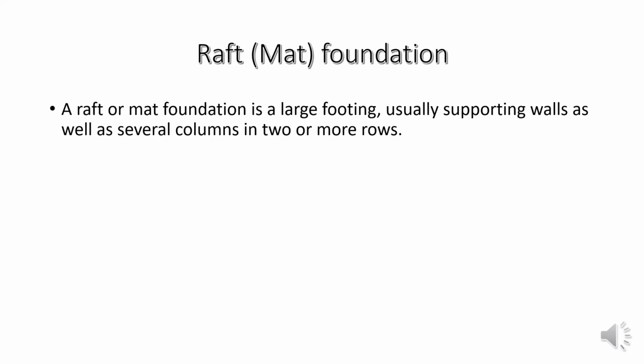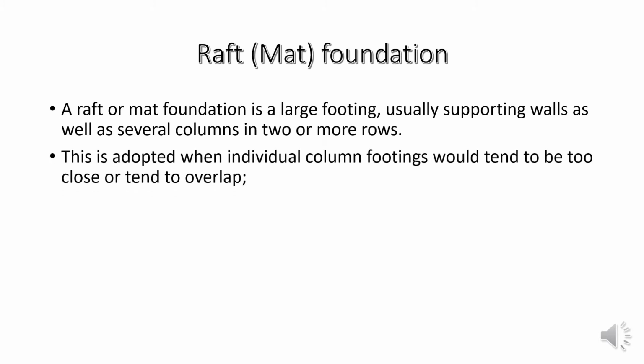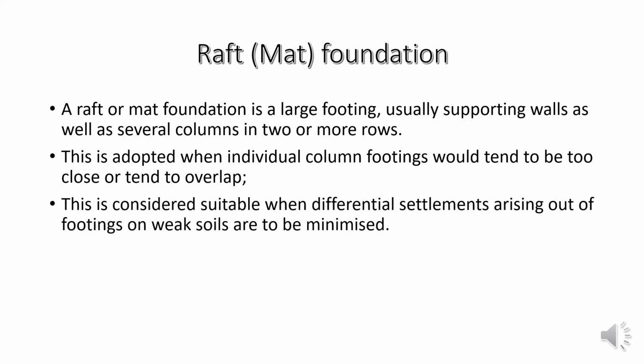Raft or mat foundation. A raft or mat foundation is a large footing, usually supporting walls as well as several columns in two or more rows. This is adopted when individual column footings would tend to be too close or tend to overlap. This is considered suitable when differential settlements arising out of footing on a weak soil are to be minimized.